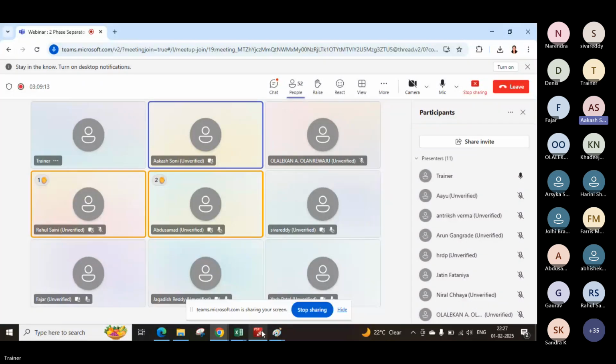Just a quick overview. Suppose you have a flare tip open to atmosphere. At the end, suppose your PSV is located at one point and your common line is flowing for 1 kilometer and then going to atmosphere. So you know the downstream pressure as atmosphere, that is P2. Then you have to know the length over the 1 kilometer which is flowing and the changing diameters.